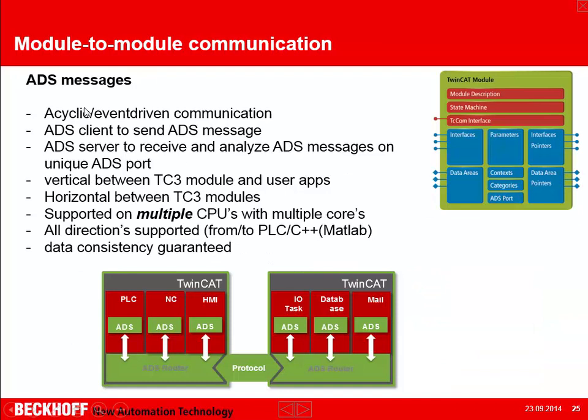And as mentioned before, send ADS messages. ADS is the backup way to exchange data between all kinds of TwinCAT products and supplement products and so on. ADS is a protocol which could be vertical but also horizontal, between kernel mode and user mode, for HMI, for your own driver. It's royalty free. We have a lot of sample code. It can be executed even over the network, but of course then you lose hard real time. Definitely it's guaranteeing data consistency because everything is serialized over that ADS protocol.